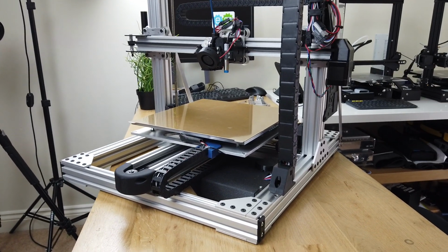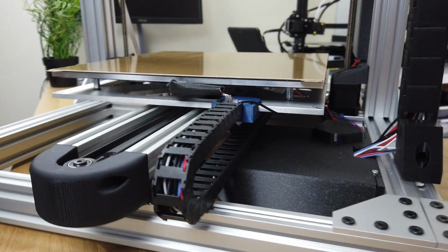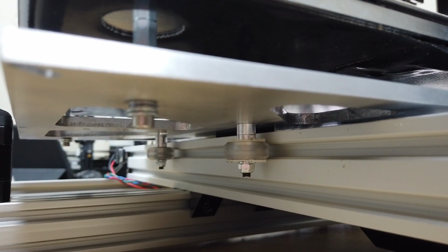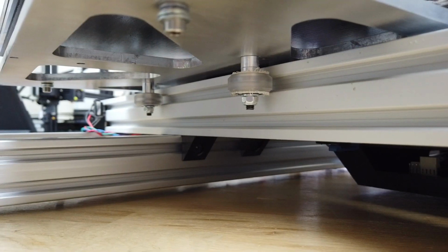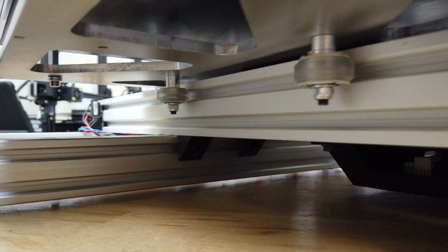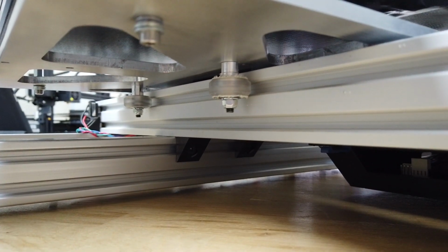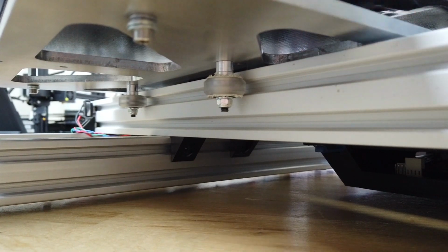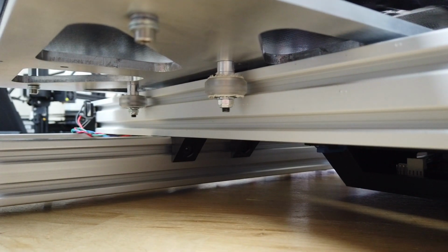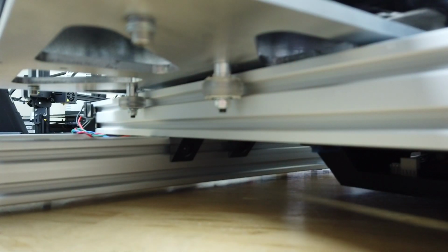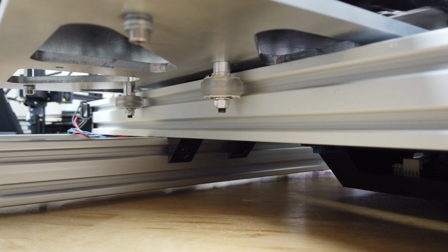The next thing I want to talk about is the wheels. So under the bed carriage, it's all held up by a few wheels. You can see the wheels. So at the moment, there's a total of 4 wheels. There's 2 each side of the carriage. Because the bed carriage is quite heavy, the wheels take quite a lot of load, and they're taking that load in a fairly unusual direction, I think. I don't think the wheels are designed to be loaded axially, so that's kind of sideways onto the wheel, which is what they are here. So the bed is obviously pushing down in that direction, and that's not ideal for the loading on the wheels.